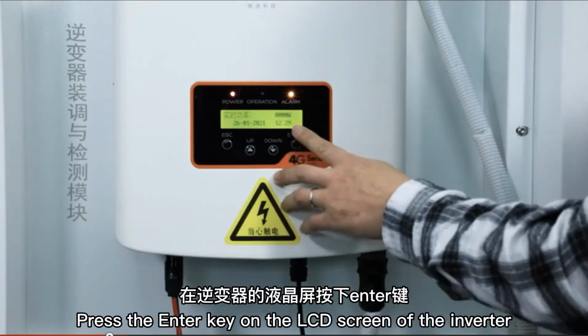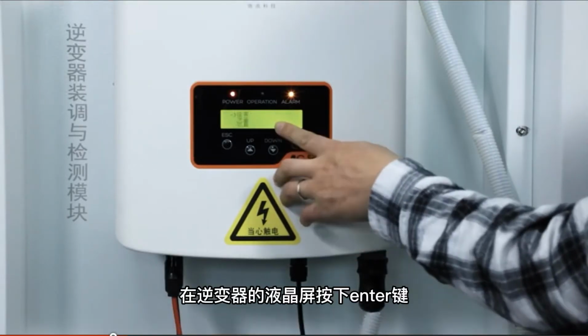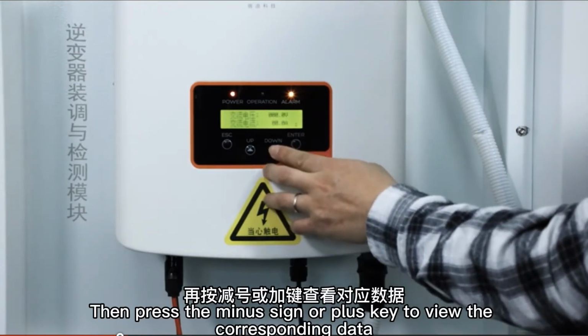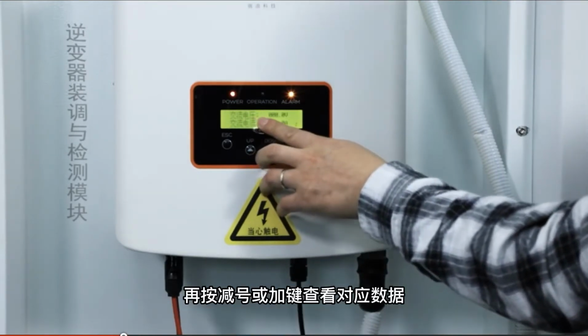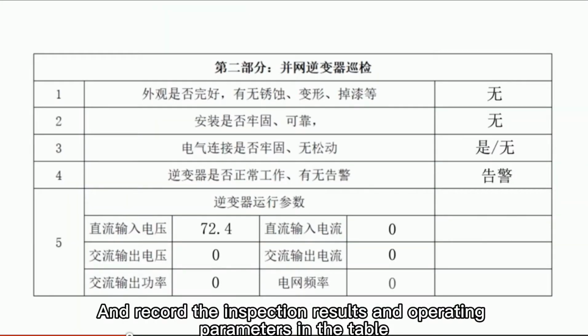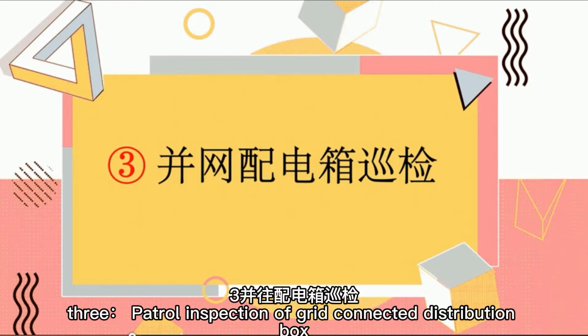Press the Enter key on the LCD screen of the inverter. Select Information. Press the Enter key. Then press the minus sign or plus key to view the corresponding data, and record the inspection results and operating parameters in the table. 3. Patrol inspection of grid-connected distribution box.